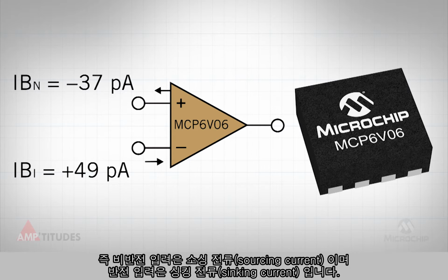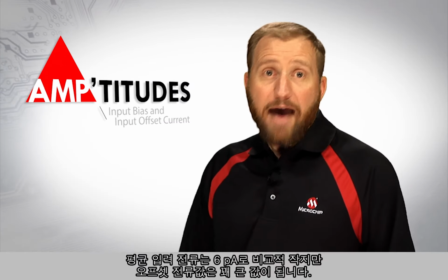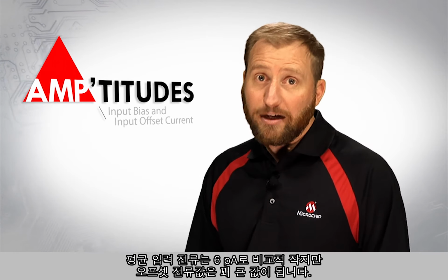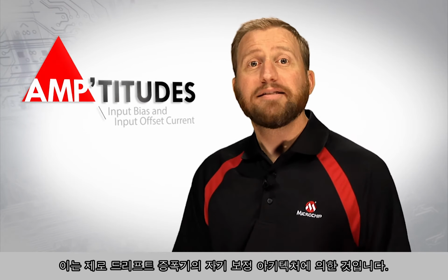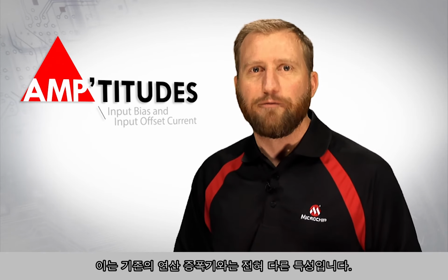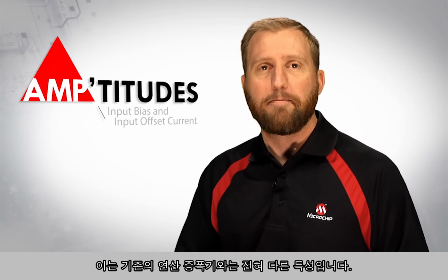This means that the non-inverting input is sourcing current, while the inverting input is sinking current. Even though the average input current is relatively small at 6 picoamps, the offset current is actually quite large. As noted earlier, this is a function of the self-correcting architecture of the zero-drift amplifiers and is uniquely different from the characteristics of a traditional op-amp.